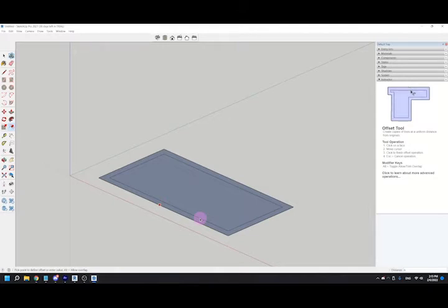One thing I've seen students do, which is going to cause this program to error, is they put 2 apostrophes as a mark of inches when that's not how you would type it in. If you wanted to put a unit marker, you're going to put a quotation mark. A quotation mark is very different than 2 apostrophes. So if you hold shift and hit the apostrophe key, that would be recognized as inches.